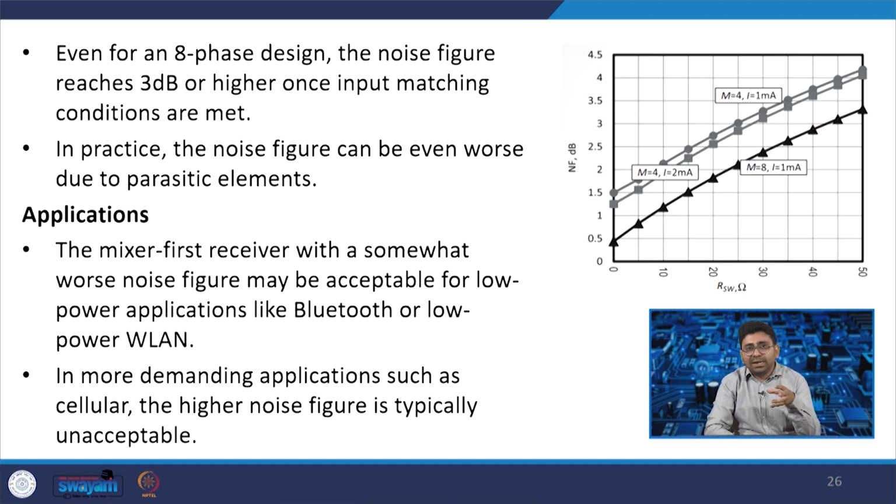So where the higher noise figure for IoT application is acceptable, at that time we can use a mixer first receiver architecture.